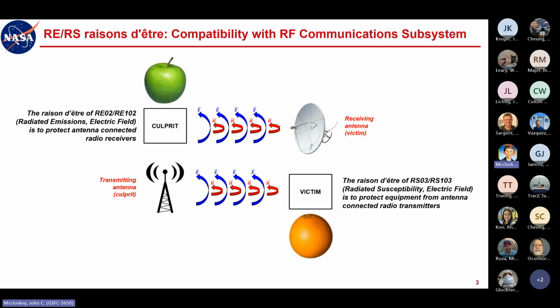So the context of applying the Mil Standard 461 to my approach to testing my transponder is that, okay, if you want to be able to fly on any military platform, you have to meet this radiated emissions limit, this RE102 limit, across the board, across the whole frequency spectrum. And then if you comply with that limit, then you're basically okay to fly on any candidate platform. I mean, painting with broad strokes here, but I think that's the general approach in that kind of context.